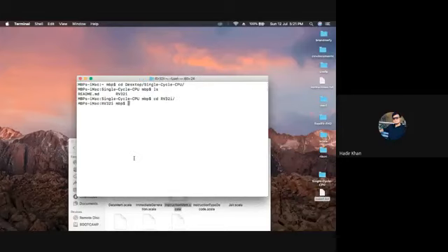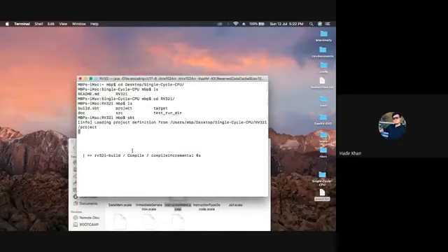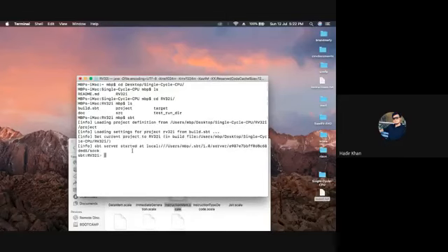All right, why the RV32i folder? Because it contains the build.sbt. So if I type sbt here, then it'll run it correctly, because SBT opens its configurations on the build.sbt file. So hopefully we can get this done. So now SBT is running and it's initializing some stuff here. All right, so we are in the SBT, and now we can type test:runMain datapath.Launcher. This opens our test bench, which is written as top.